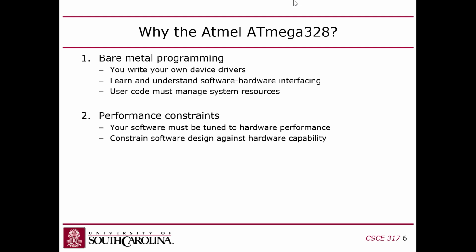You also have to manually manage the system resources, like memory and the peripherals that are available on the chip, and off-chip peripherals. And also, the performance is obviously very limited. So you're going to have to write code that is performance aware. In other words, you may have to tune your code a little bit to make it meet certain deadlines required by the application or by the device, the peripheral, the I/O device that you're communicating with.